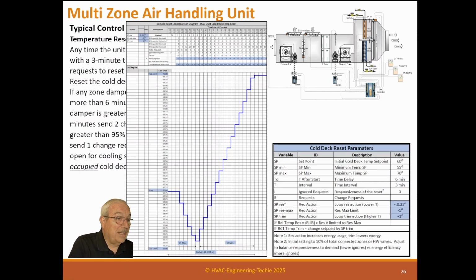Up doesn't mean anything because the boxes can switch all to the heating side if it's too cold. So we want to go up because we want to save energy, but it doesn't matter if it goes. We could change this. We could get this more aggressive. We could make this 1.5, cut it down a little bit. We could make it even 2, cut it down a lot if you want to. But this is within the realm of the cooling of the space.